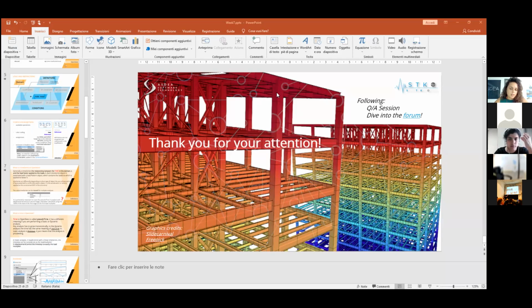What will happen is that your pushover will not start from 0 when it's drawn on the graph. When you plot the pushover, that's reaction force against displacement, but if you plot, for example, your displacement against the time step, it will not start from 0. So you will have a graph that's floating in space.